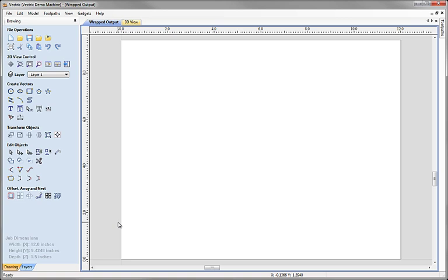Finally, the depth of the part, the Z depth, is the equivalent of taking a 1.5 inch thick piece of material and again just rotating that around the center so that the total of that would be 3 inches. So that's how we've specified these values here, and that's been picked up from those numbers that we entered into the Wrap Job Setup gadget.